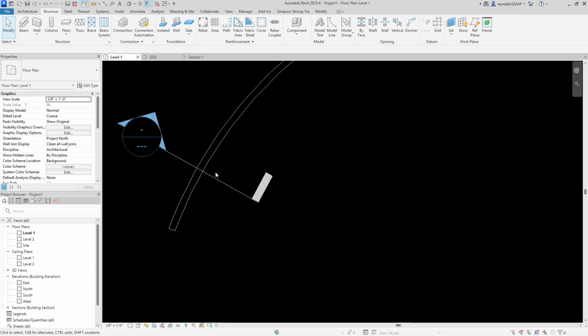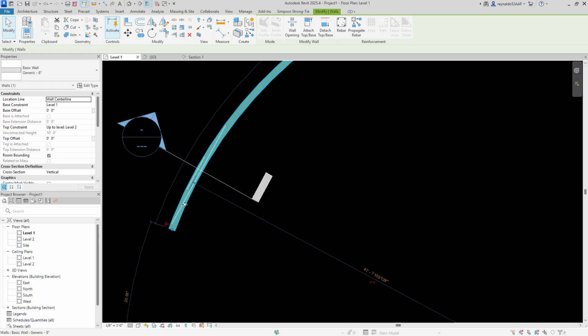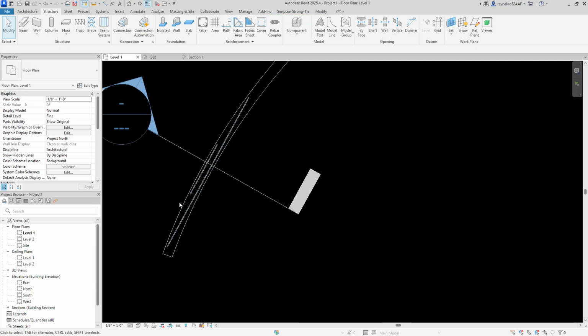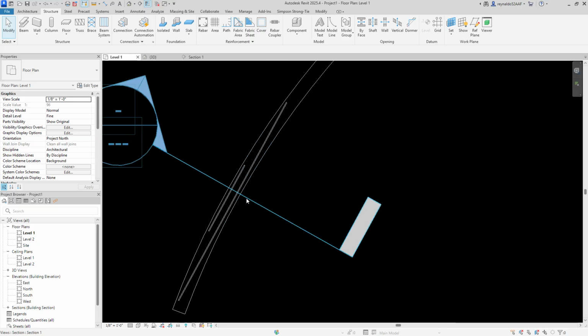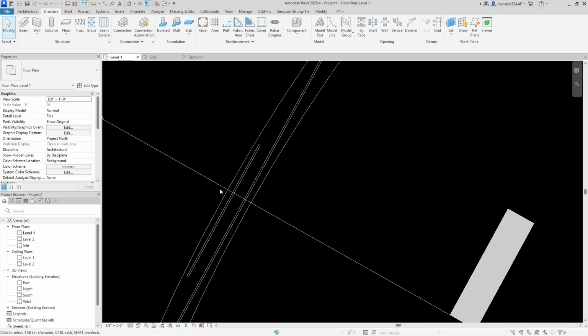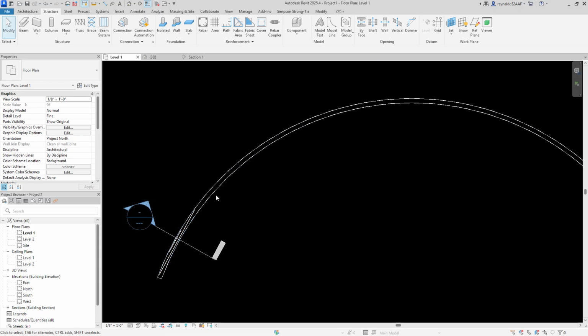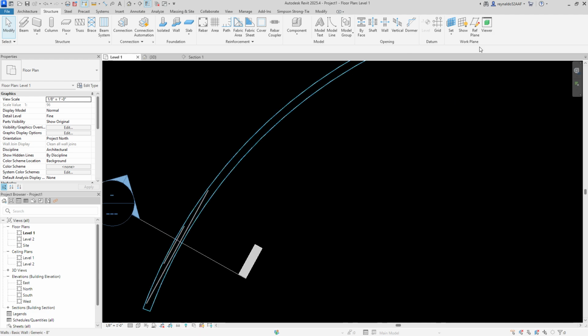you will see that I go to Find View. If I change this view, so right now it's on Hidden View, we'll change this to Wire. You can see what happens here. So the rebar, we did our cut section right here. So at this cut section, as you can see, the rebar is parallel to this cut. However, it doesn't continue the host curvature. It just keeps on going straight.